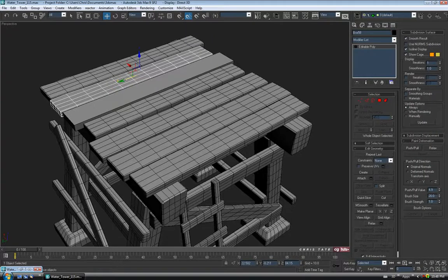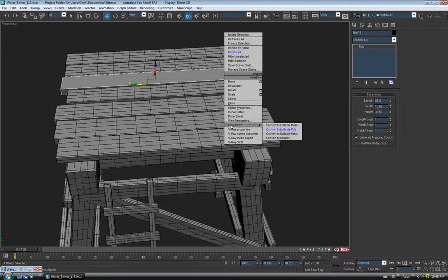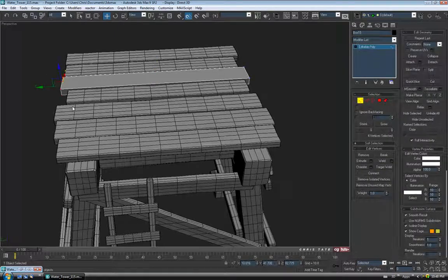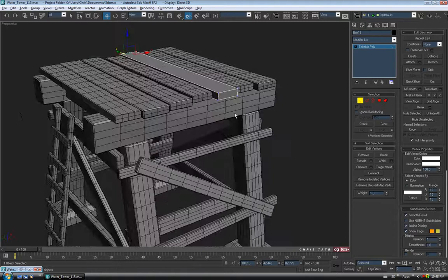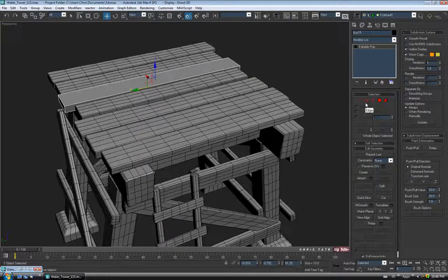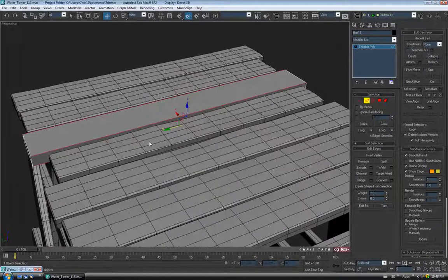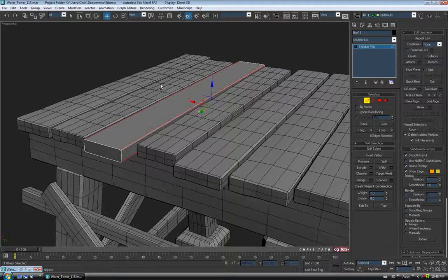Alright, so I'm just going to grab that second one and push it back a bit, and grab this one, and just convert it to poly and make the left side just a tiny bit longer than it is. Alright, I think I'll leave this end as is. And we'll just do this for the last time. Alright, maybe around 0.3 or so.